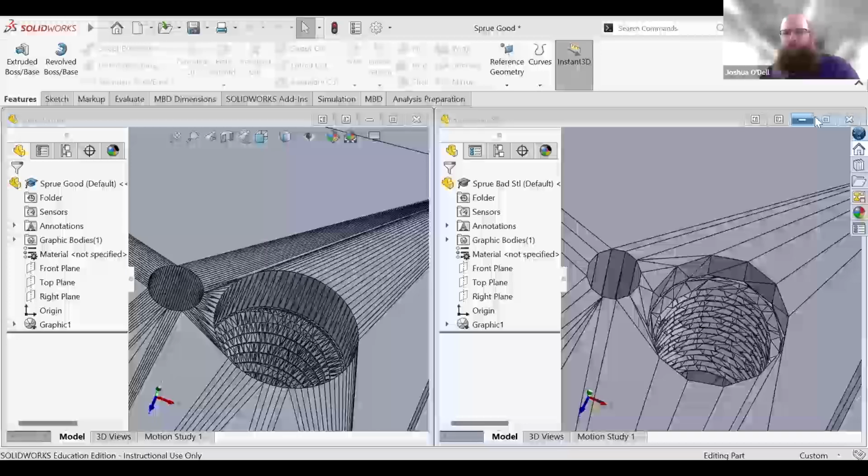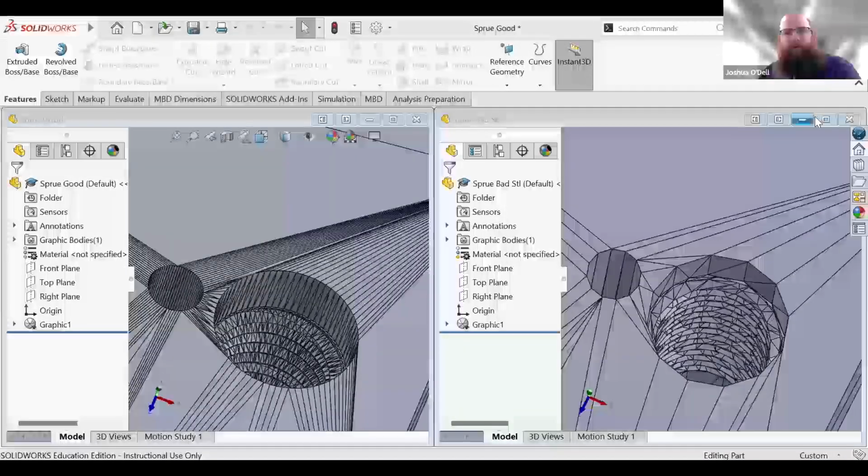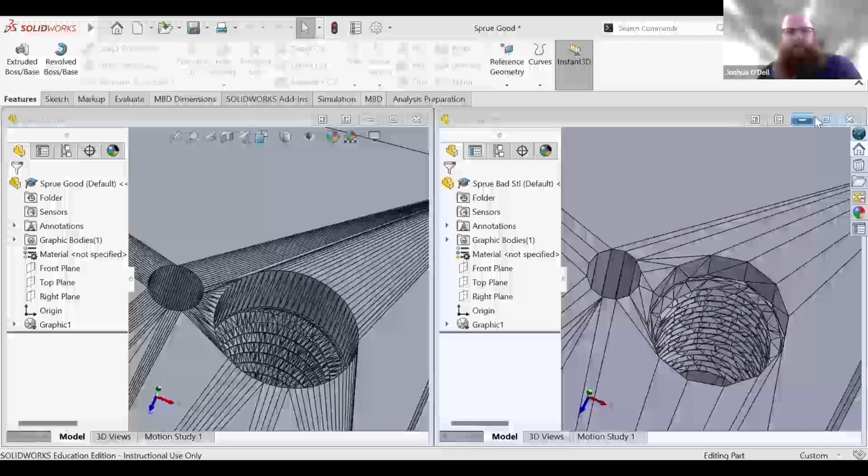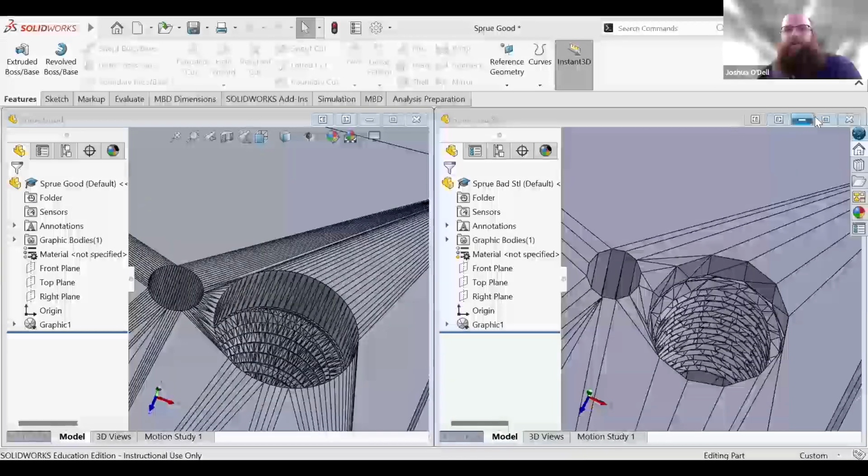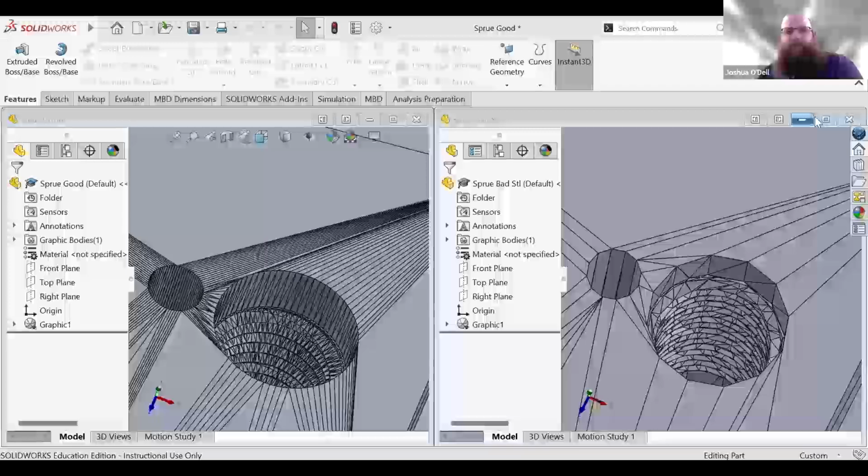There's been a few pattern materials that we looked at that had really, really good ash content, but when we started to heat them up, they would expand way more than a lot of our other materials would. And lo and behold, they ended up cracking shells just because it wasn't collapsing soon enough and was expanding way too much for the shell to handle. So either dip it more times, or significantly more times, and hope for the best, or disregard it entirely.